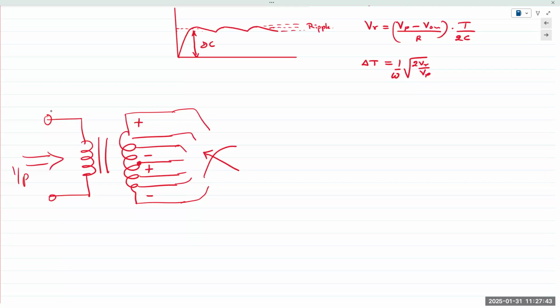It's like a switch. You move the switch, and depending on where it makes contact, you're seeing a small portion of that secondary winding. You could get an output of 1.5 volts, 3 volts, 4.5 volts, 6, 9, 12, 15 volts. So multiple taps in the secondary winding. But that's what it means.